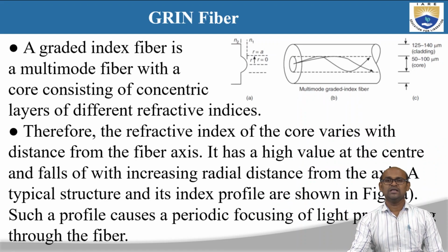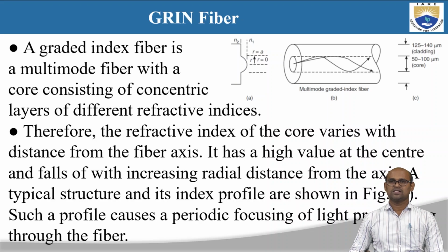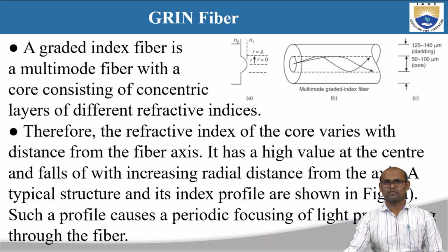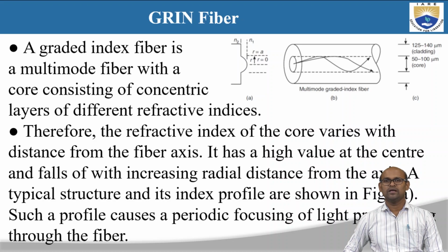Okay, so a graded index fiber is a multimode fiber, right? So that is about propagation of light in the multimode step index fiber. Now let us discuss the graded index multimode fiber. A graded index multimode fiber has a core consisting of concentric layers of different refractive index. So first of all, this is a graded index fiber.